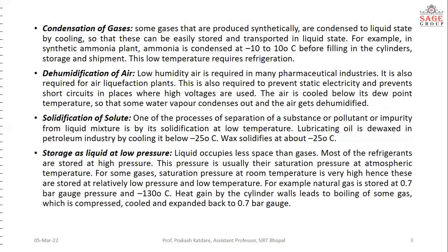Then dehumidification of air. Low humidity is required in many pharmaceutical industry. It is also required for air liquefaction plant. This is also required to prevent static electricity and prevent short circuit in places where high voltage are used. The air is cooled down below its dew temperature so that some water vapor condenses out and air gets dehumidified.